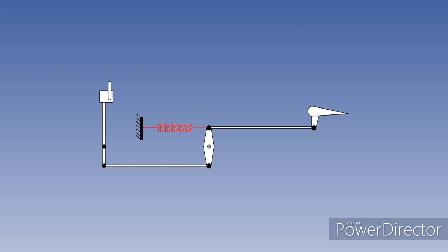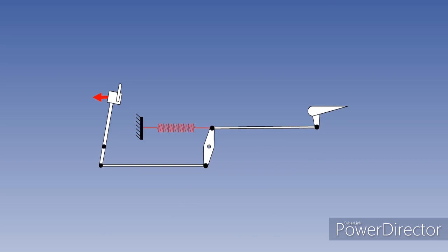Designers can modify the stick forces, if required, to give adequate manoeuvrability throughout the entire flight envelope. The first device that can be used to tailor the control forces is the downspring. The downspring is used to increase the airspeed stick force stability. The downspring consists of a preloaded spring attached to the control system that tends to rotate the elevator down. The effect is to contribute an increment of pull force independent of control deflection or airspeed.